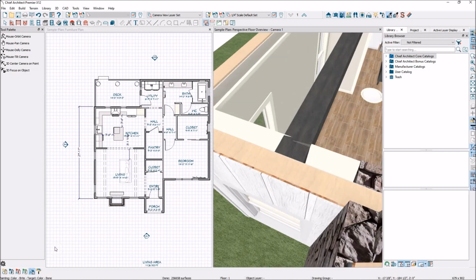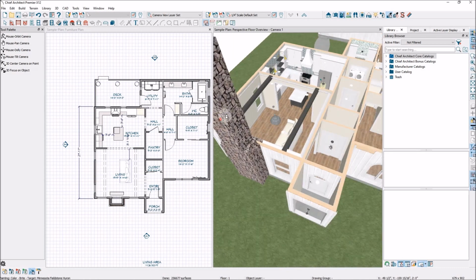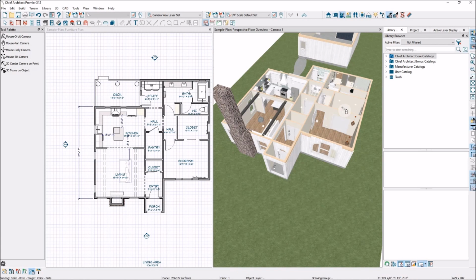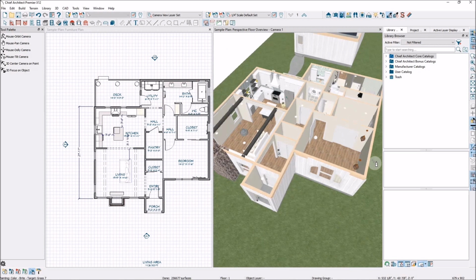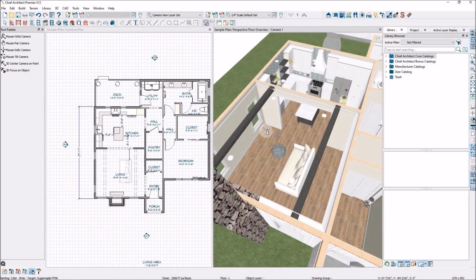And now if I go here with this selected as project, every single thing in my entire project that's painted this color will change. So I can just click that window casing there, and every single bit of wood or anything else that was painted that color inside this project has now changed. Every window, everything. So that is a super easy way to change everything in the project. You can do it by component, by object, by room, by floor, or by project.